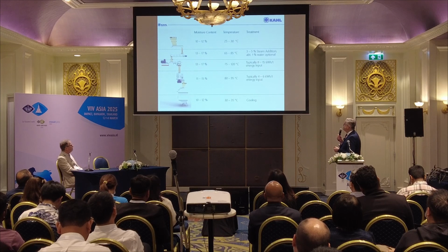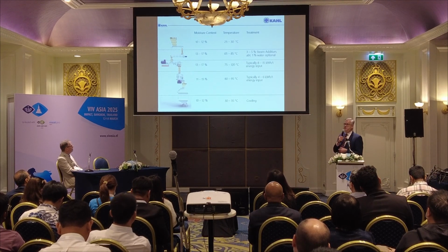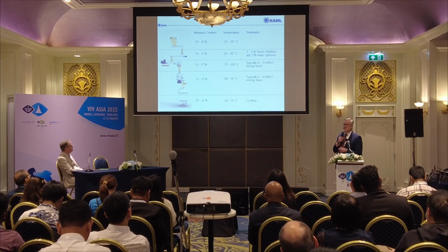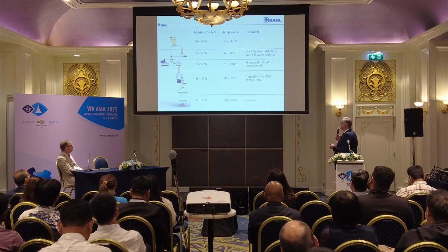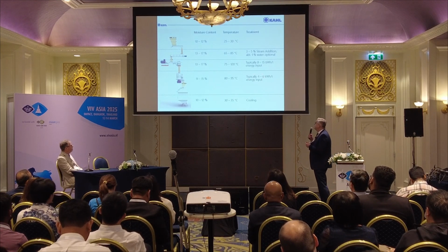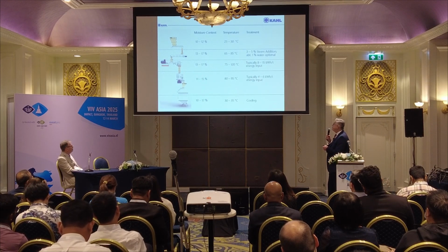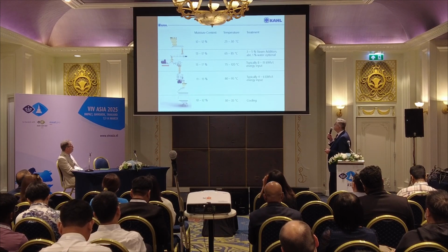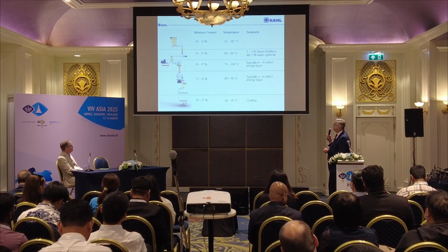Now I go immediately to the pellet mill energy input. The pellet mill is not compressing anymore, it's only shaping. So you can reduce the effective press length by 40%. The stress on the pellet mill is much lower, only 4 to 6 kilowatt hours per ton typically are used in the pellet mill. And you make very high PDI values with this combination. The pellet mill is just shaping the material with very low energy input, because all the work has been done by the expander already.